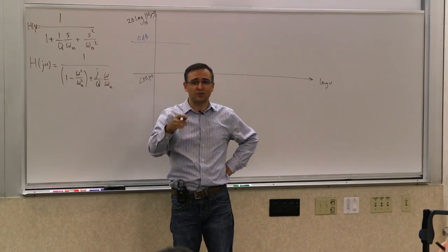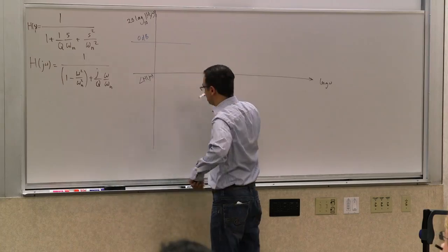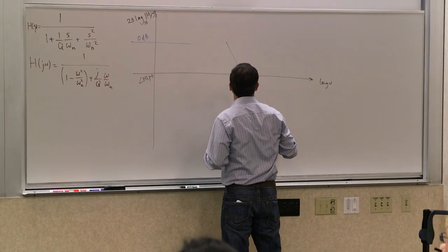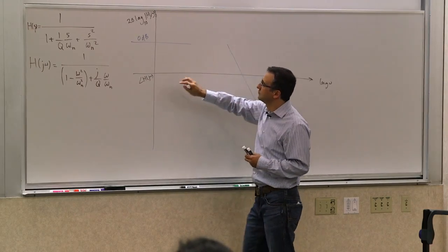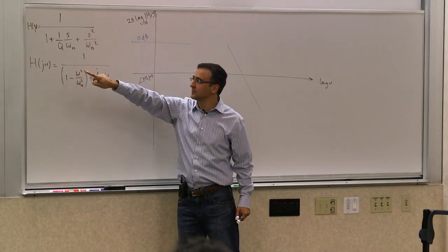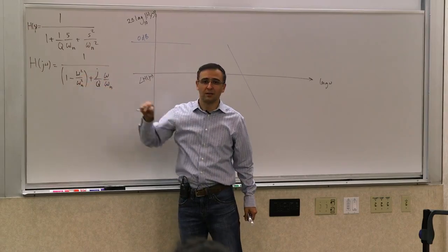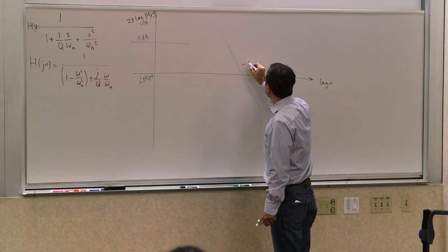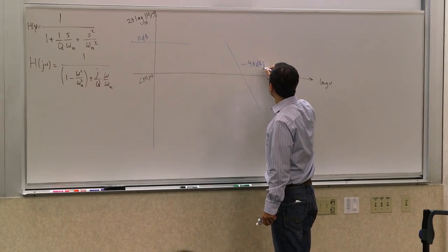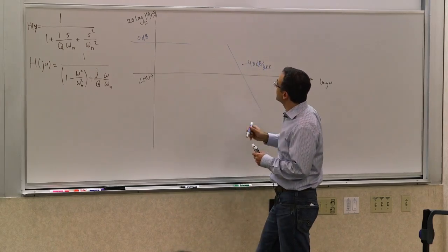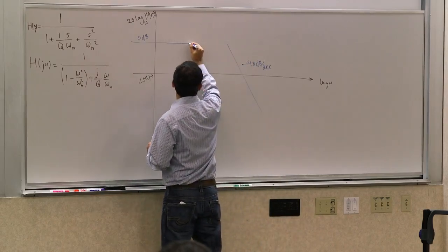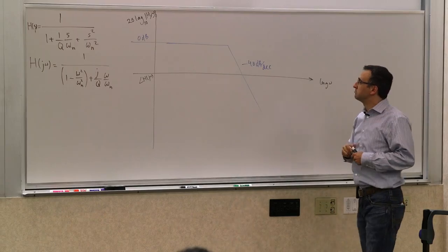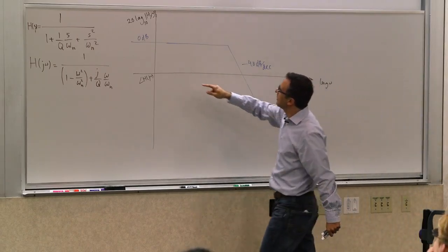At omega squared or S squared, the rate is n equals 2, or more accurately negative 2: negative 40 dB per decade. So you have these two asymptotes, and if you plot it this way, maybe my Bode plot looks like that.